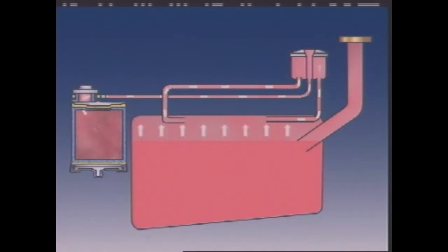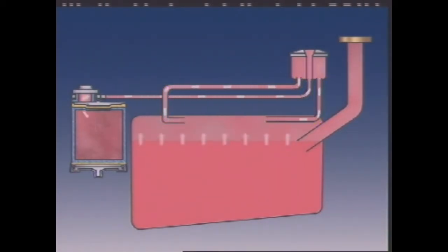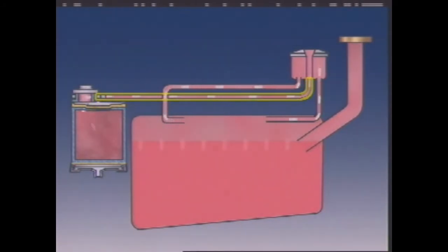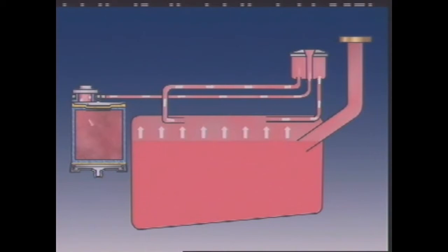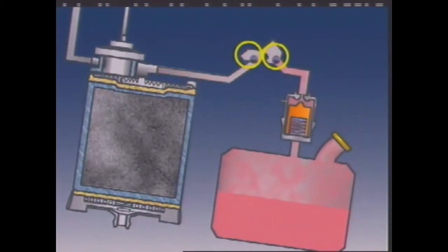A liquid vapor separator may be connected to the tank by a number of tubes. This separator allows liquid fuel to separate from the vapors and return to the tank. A vapor line is connected to the vapor space in the tank, or the liquid vapor separator. It carries fuel vapors from the tank to a storage volume. This vapor line can incorporate check valves. If the vehicle is tilted too far from the horizontal, they stop liquid fuel entering the storage volume.